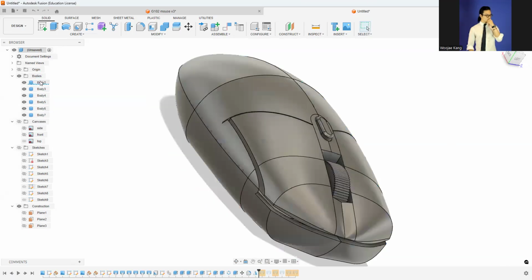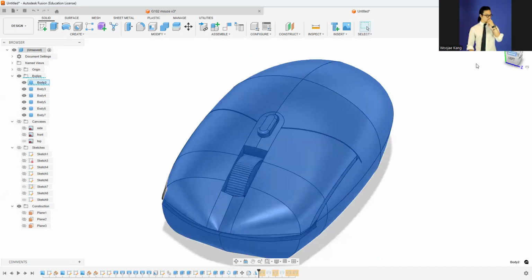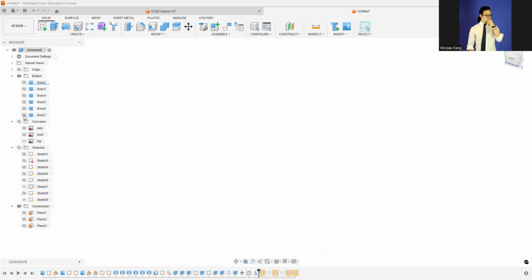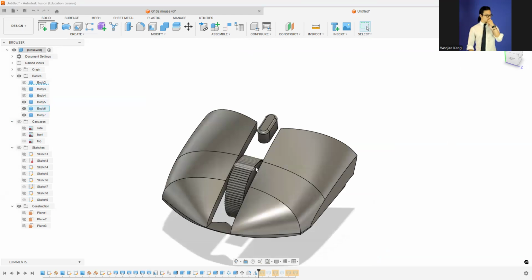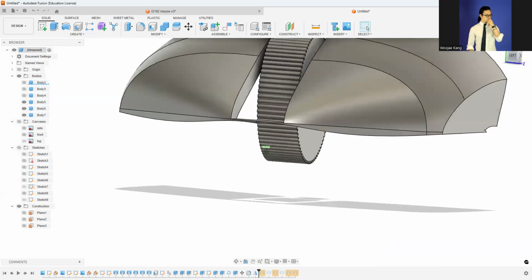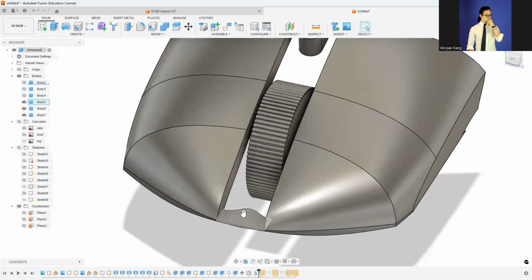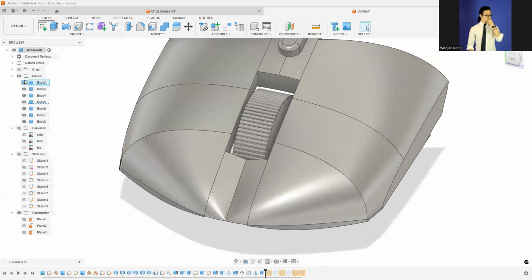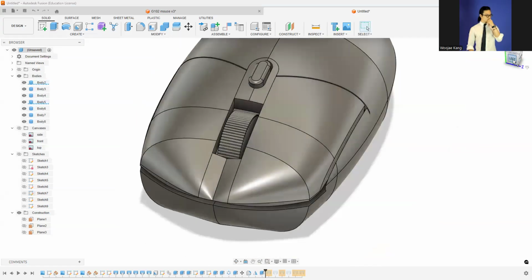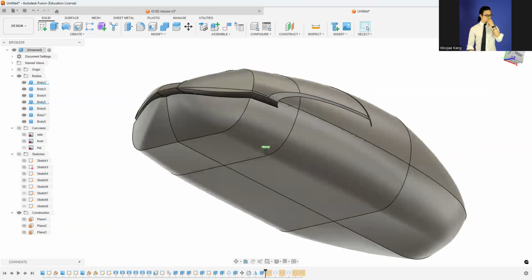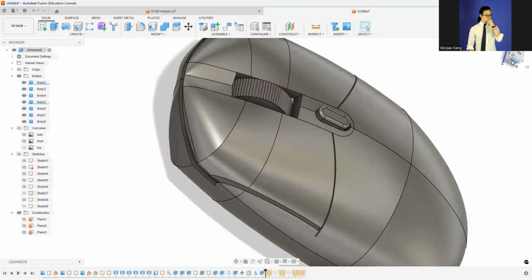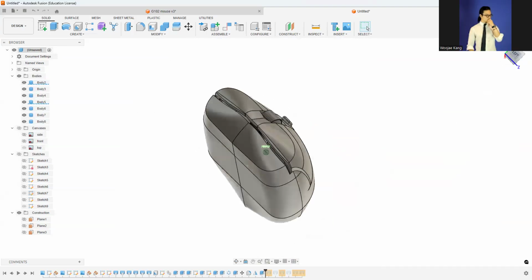Then now you'll successfully have the main body, main section, wheels, and the mouse buttons. Oh, maybe this is not fully disconnected, so use the extrude tool for a full cut. And now we have succeeded in getting the full shape of the G1 Logitech mouse.